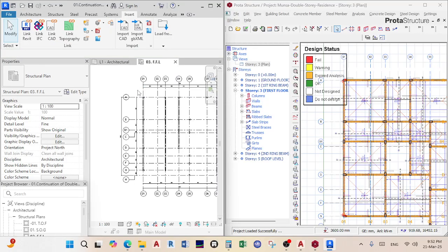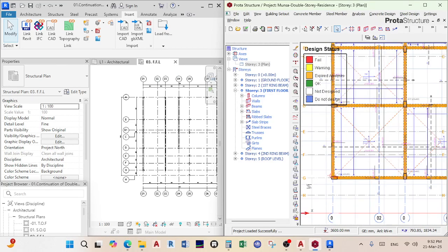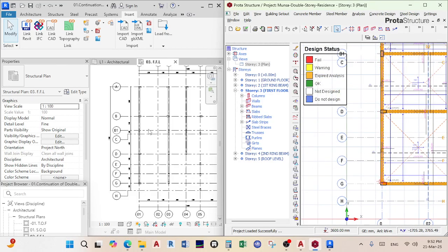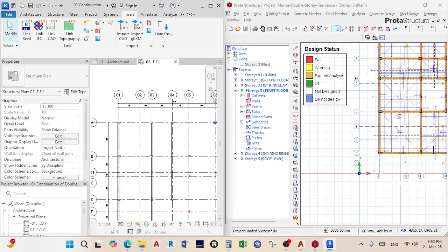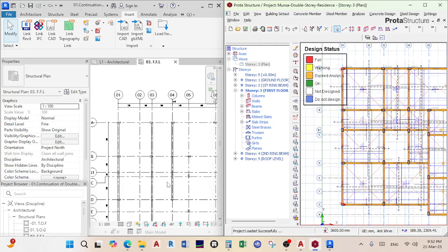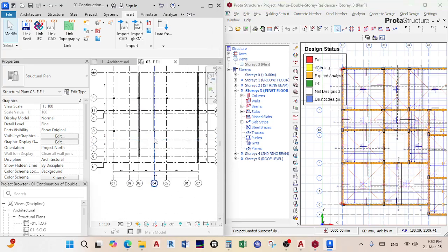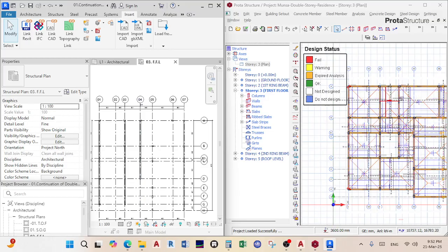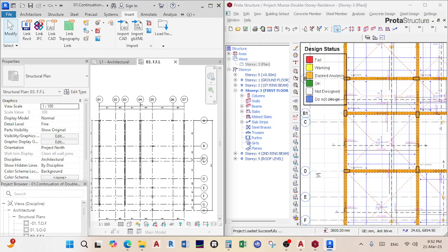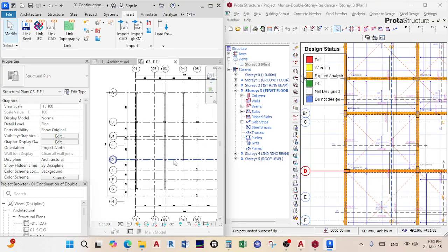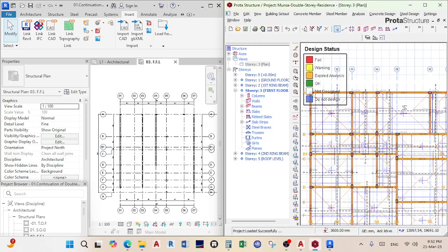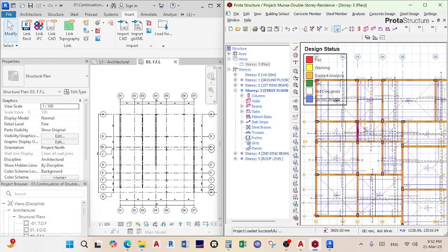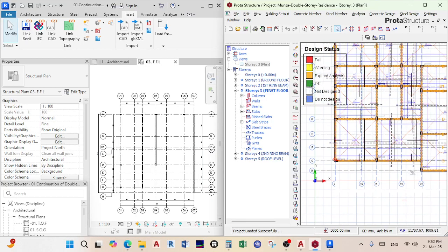So what we're doing is, here in Prota we can see that from 1 to G, that's where this beam in the y direction ends. Also here 1 to G, good. And then the next beams appear in 3. 3G, from 3 to G, okay, we're good. And then in 4 here they end at D. 4 they're ending at D. Cool. How about 5? 5 they're starting at B up until H.